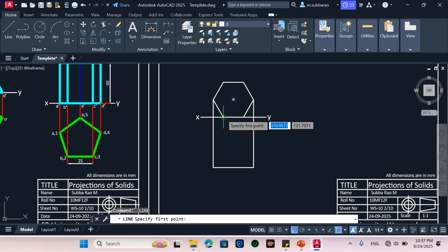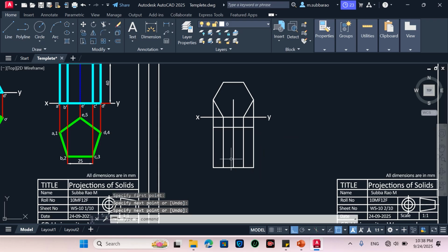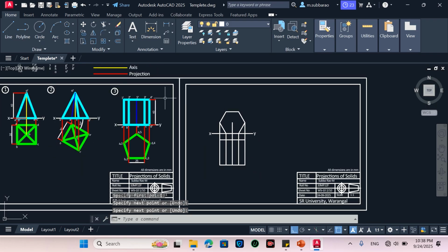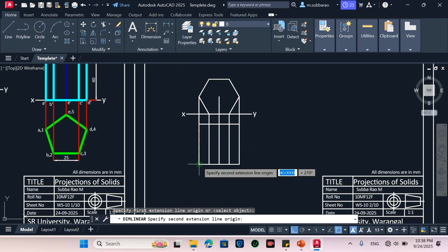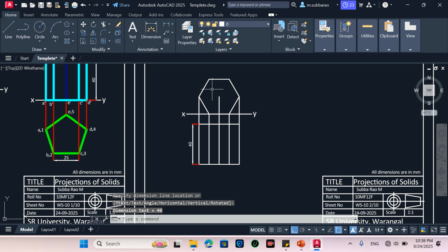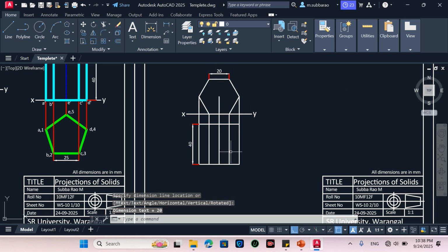this is the base. So again if I draw here, this will become the top view. Draw the projections, and here is the axis line, and this axis line I directly draw, and here I will see another top view of this. So with this I can complete the third diagram. But before I complete, I give the dimensions. This is the 40 mm dimension, and they gave the base edge dimension as 20 mm, and then I need to give the nomenclature.